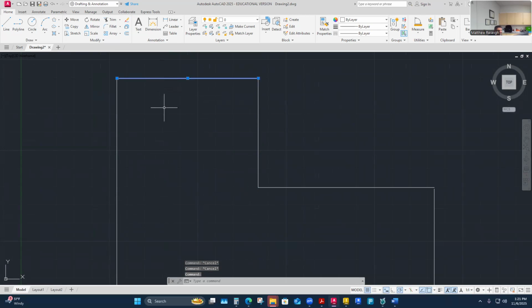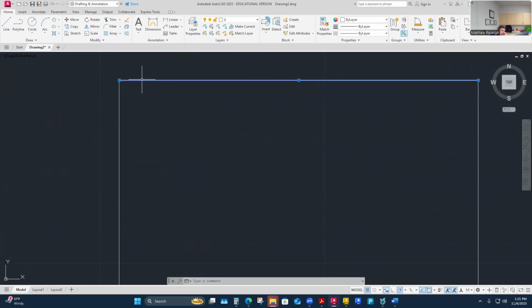I just come back in and I'm selecting this geometry that I drew. It has these points. These are called grips. I can grab this line by those grips, and a line is going to have a midpoint and endpoints. That's just the common grips associated with a line. I can come in here to a grip and move it by its grip. I can actually click on it, and now I have what's called a hot grip. It's gone red.